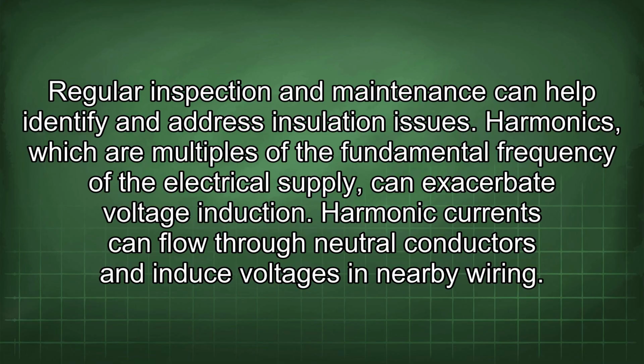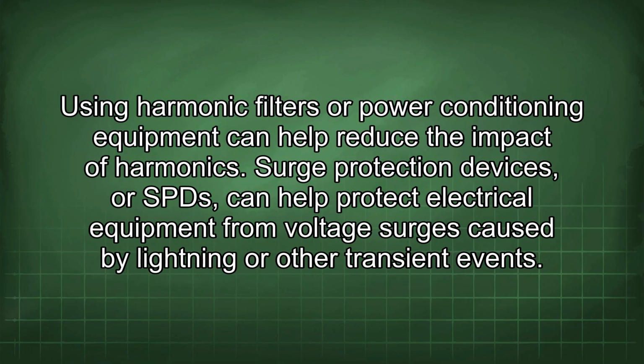Harmonics, which are multiples of the fundamental frequency of the electrical supply, can exacerbate voltage induction. Harmonic currents can flow through neutral conductors and induce voltages in nearby wiring. Using harmonic filters or power conditioning equipment can help reduce the impact of harmonics.